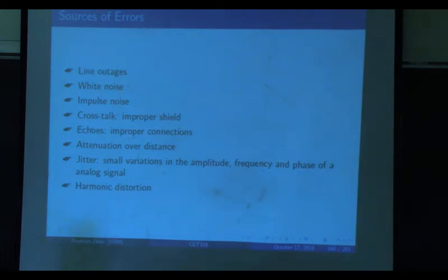A log book means when you start, you write everything, the raw data. You observe something, you write it down. Something weird, you write it down, and then you discuss everything. Then you process this raw data and write your lab report. You need to attach your log books to the lab report. If you do a circuit, you write down voltage, current, and so on. But for this one, you may need to record the screen of the oscilloscope, so you can take a picture of that. You need to keep your original picture in case I ask you to show me your image.